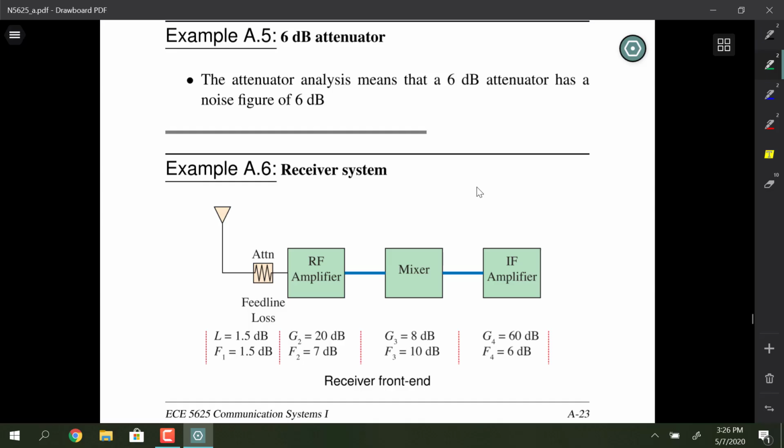Some of you have maybe experienced some of that, but yeah, decoupling is a common thing. Actually, it's a really important thing in RF. Decoupling of all kinds is important because power can pick up signals. You can get RF signals onto your power line, and then you've got a real problem because it can go from one subsystem to another if you don't decouple things properly in the layout.